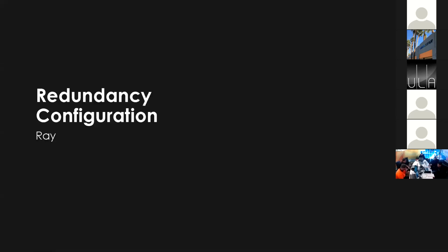So the moral of the story is config files: unless you know the type of IC and the way that your ICs are basically mapped out driving your LED chip inside your modules, it's kind of hard to build your own config file. There are some smart settings in there, and as the Nova guys said, they can do some advanced training on building your own RCFG file. But 99% of the time, you're going to have the most optimized file that comes from the factory. And sometimes you might want to go in and tweak the refresh, and you'll lose some bit of brightness. But unless you really need to change it, I wouldn't recommend playing with your RCFG file, especially now.